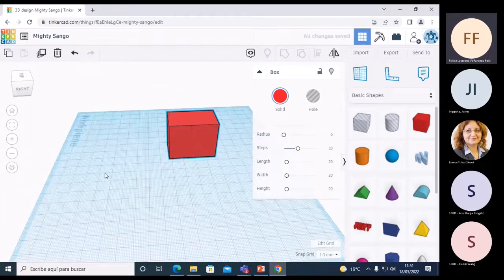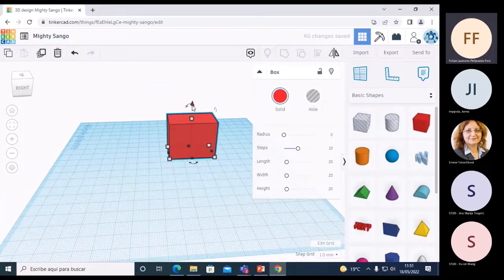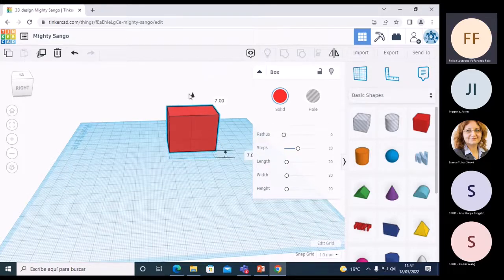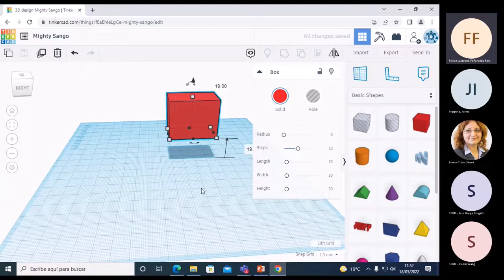And if you check, I will rotate it. There is a small black triangle, which is floating in the air above the center point of the top plane. With this handle, you can change the gap between the work plane and the object.